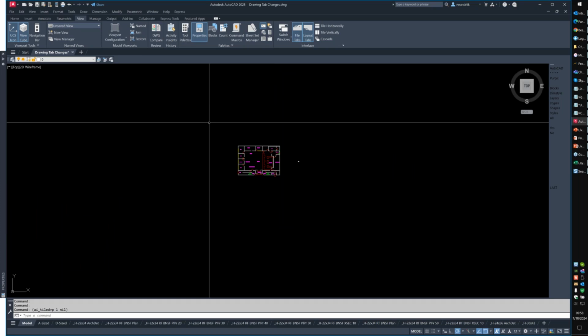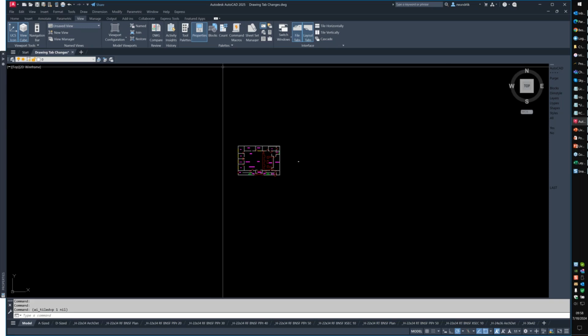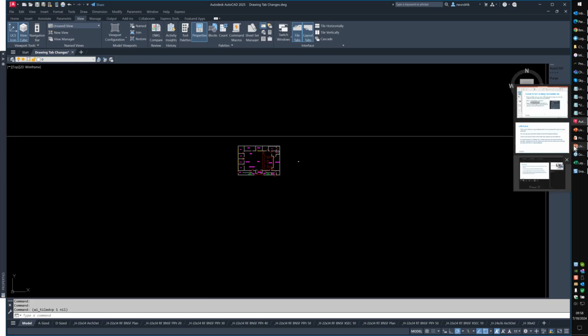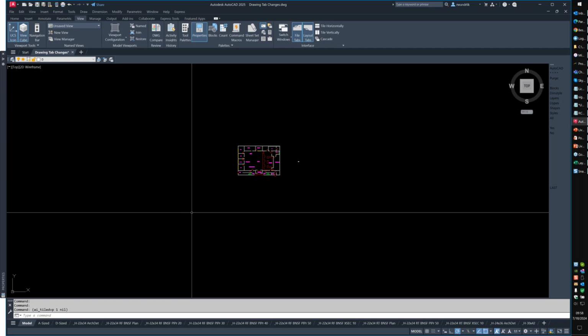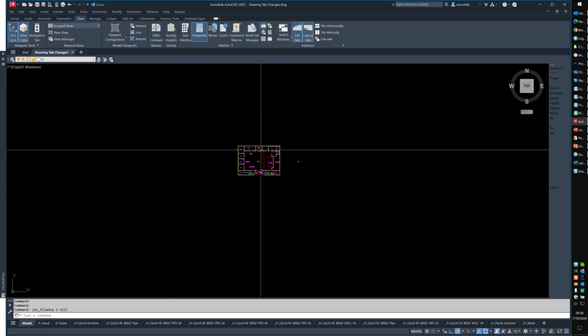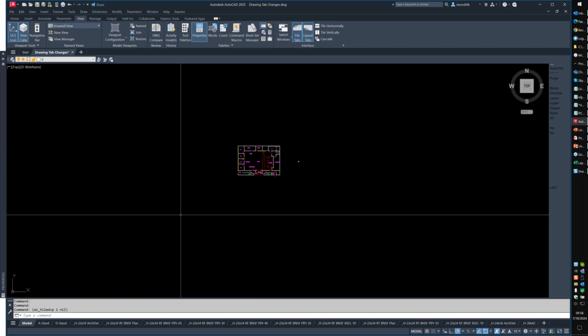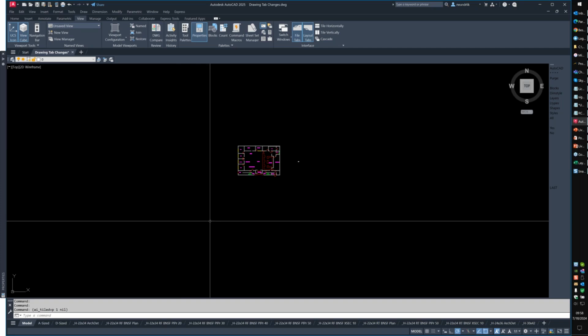All right, and Lori, we are right up on our time limit. This has been a really good one, guys. You guys have asked a lot of great questions. How can I keep the size of the drawing as small as possible? Purge everything that you can out of the drawing. Don't explode your blocks, because every time you explode a block, you make your drawing slightly larger.